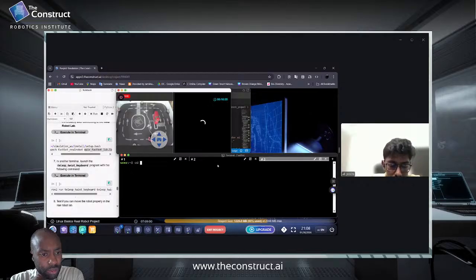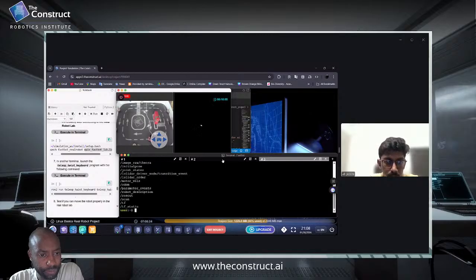Is the robot responding to you? No, it's not. Okay, can you run ros2 topic list? We just want to see if all the topics are available. There has to be space between topic and list. Okay, so you should be connected. So try running teleop. So use teleop to control it. Do you know the command? It's right next to... yeah, copy that one.